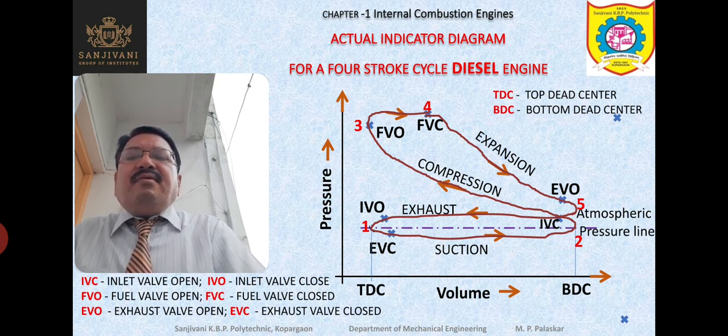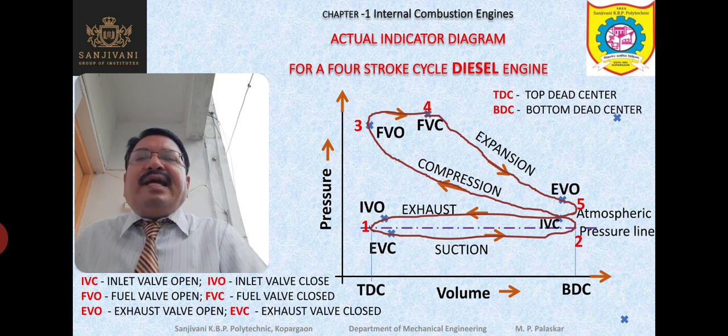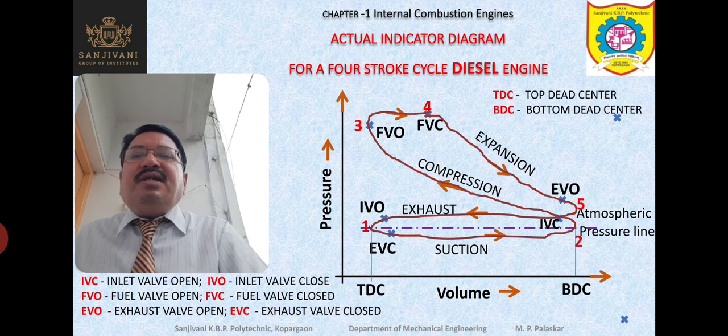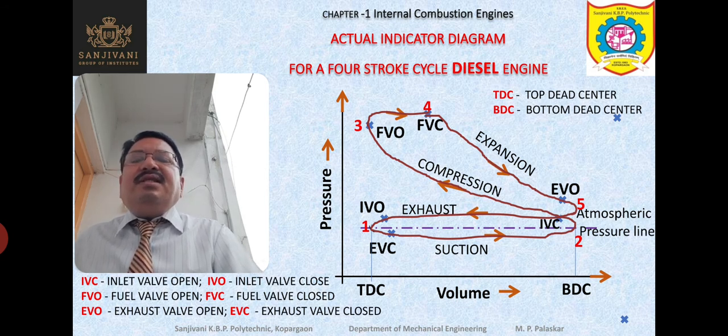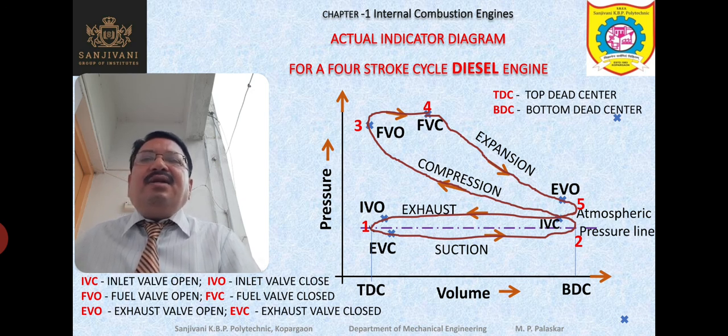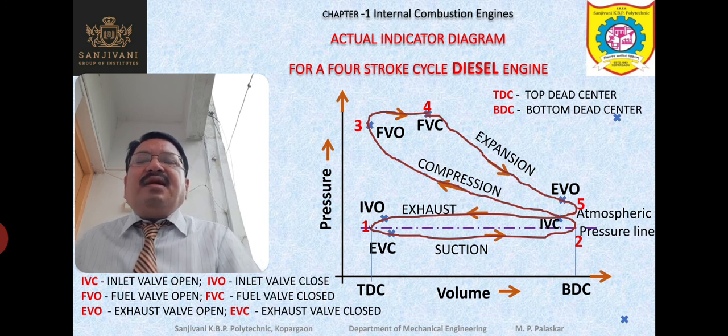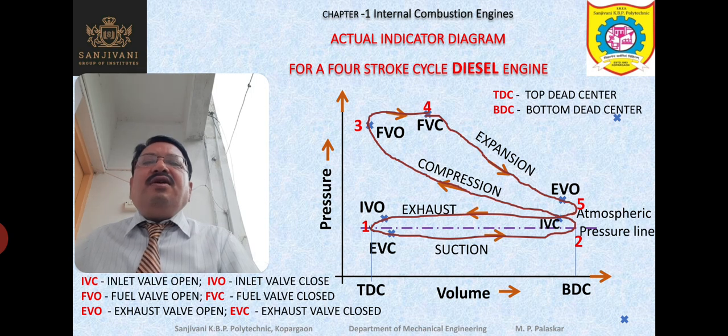So when the exhaust stroke ends, before the end of the exhaust stroke, the inlet valve is open. That means the inlet valve also opens slightly before the top dead center position, and the exhaust valve is closed slightly after the top dead center position. So the valves in the actual engine are not exactly opening and closing at the top dead center position or the bottom dead center position like the theoretical case, but in the practical or the actual case you will find that there is some angle difference, there is some lag between the top dead center or bottom dead center and the opening and the closing of the exhaust and the inlet valves.